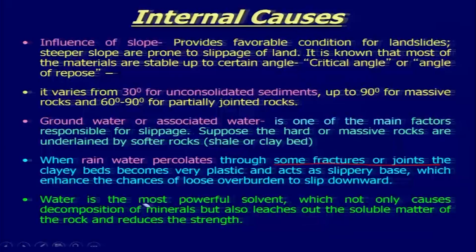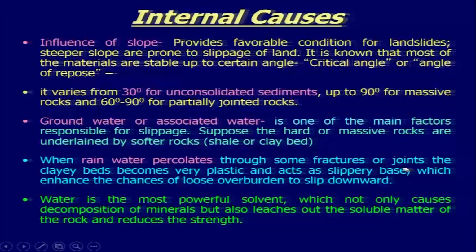So, water is the most powerful solvent which not only causes decomposition of the minerals, but also leaches out soluble matter of rock and reduces the strength. So, this is another important parameter which we should keep in mind, because this can result in the reduction of shear strength.